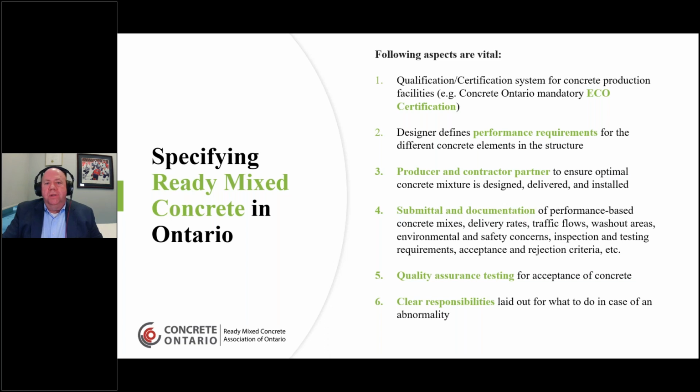We're going to get into submittals to try and show that we've identified what the performance requirements are. And then we're going to get into quality assurance testing. So again, testing remains one of the critical issues for our industry. As we talk about low carbon reductions, one of the major levers that we're pulling, quite simply, is trying to optimize the mix design for cement content. And we're trying to optimize or reduce for cement content because it has a fairly significant impact on the carbon intensity. So we have to have accurate concrete testing in order to do that.